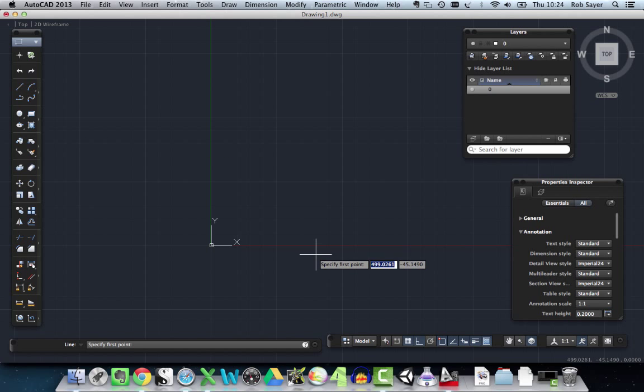So I'm going to start at the bottom of my wall, and the first section I want to draw, and I'm in Ortho Mode, so it's going straight up. The first section I want to draw is 350mm high. So if you remember, start your point, start to draw, type in 350, enter, and it draws you a line.